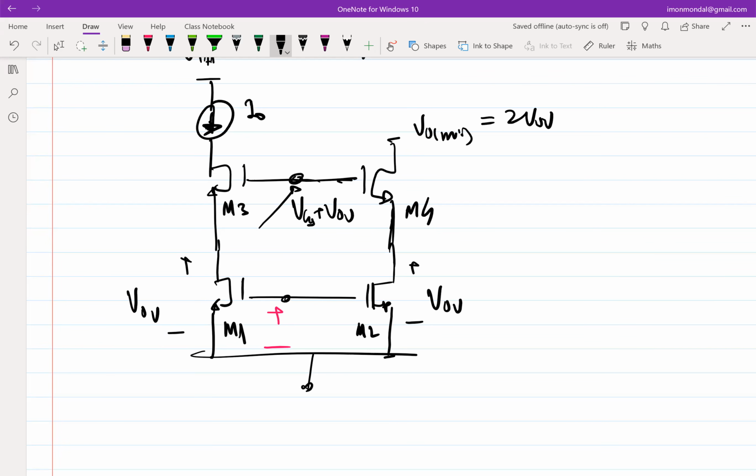Increase the voltage, increase VGS, right? So again, the drain is increasing. The information that I am getting is that the drain voltage of this is increasing. The action that I need to take is to increase the gate-to-source voltage of M1. So what is the obvious thing to do? Connect this, right? So connect this. Okay, fine. What about the cascode transistor voltage as VGS plus V overdrive?